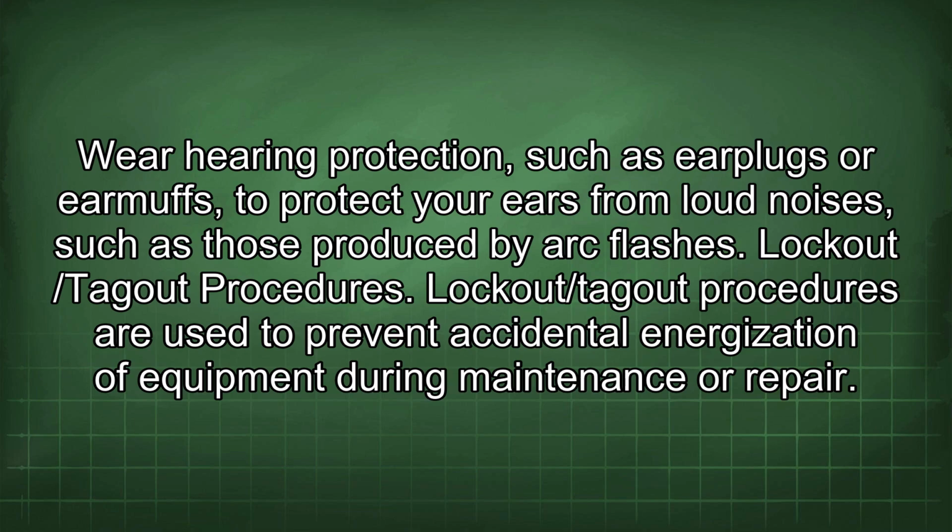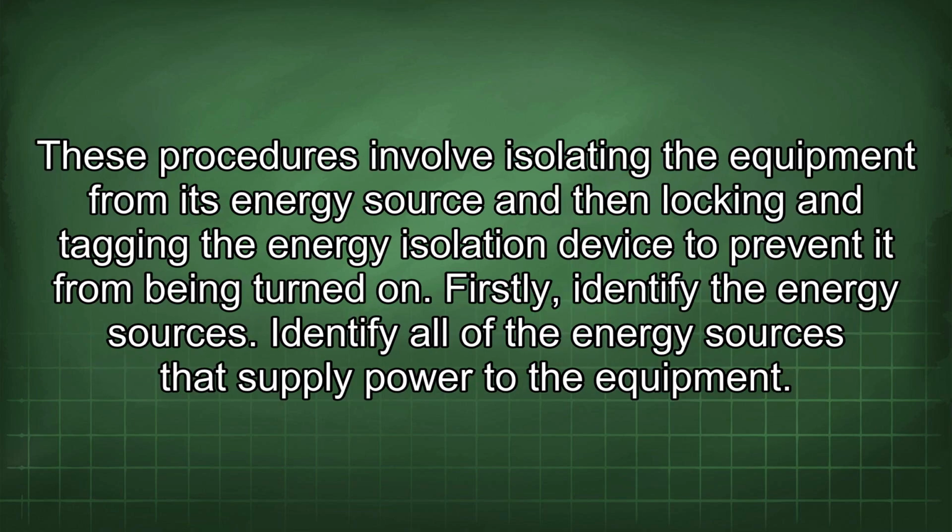Lockout/tagout procedures. Lockout/tagout procedures are used to prevent accidental energization of equipment during maintenance or repair. These procedures involve isolating the equipment from its energy source and then locking and tagging the energy isolation device to prevent it from being turned on.